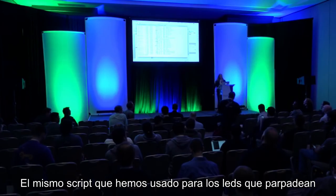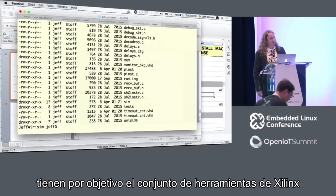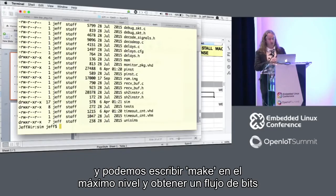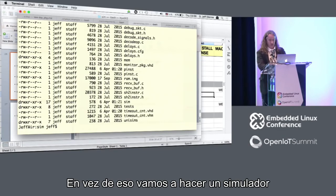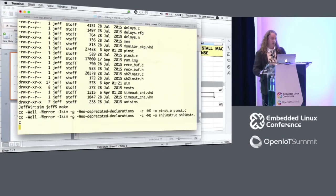So the same scripts that we used for the simple LED blinker here target the Xilinx toolchain, and we could just type a make at the top level and we get a bit stream that contains the MIMUS v2, but it takes 35 minutes to run. So instead, what we'll do is we'll make a simulator instead.